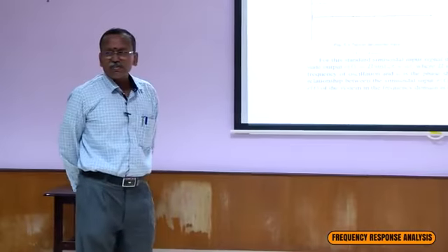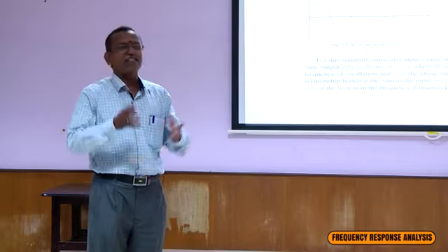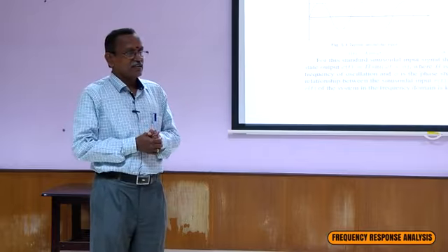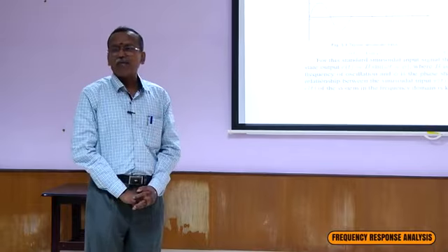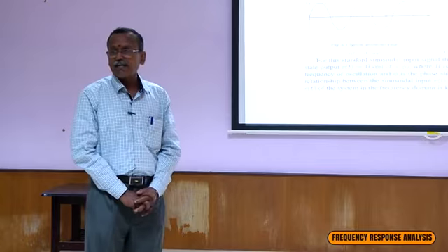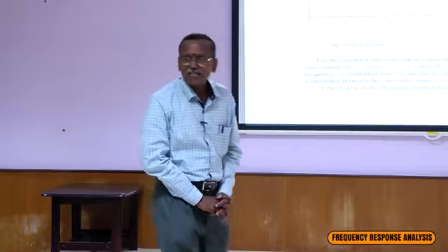What is frequency response? We give a sinusoidal input. On the output side, what is the amplitude we measure? What is the phase shift we measure? If you plot frequency against amplitude, that is called the magnitude response. If you plot phase shift against frequency, then it is called the phase response.